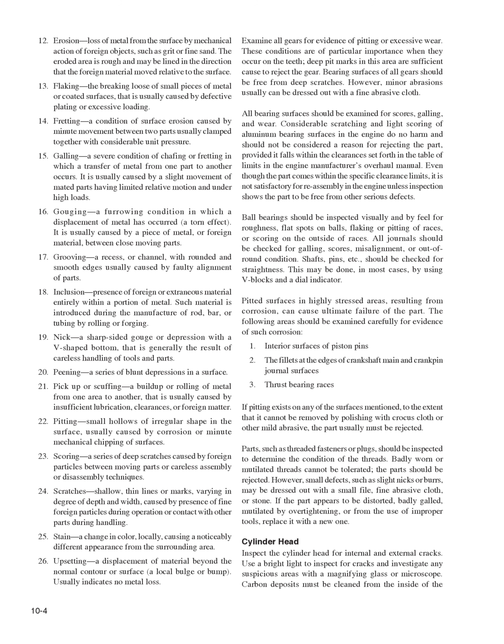All bearing surfaces should be examined for scores, galling, and wear. Considerable scratching and light scoring of aluminum bearing surfaces in the engine do no harm and should not be considered a reason for rejecting the part, provided it falls within the clearances set forth in the table of limits in the engine manufacturer's overhaul manual. Even though the part comes within the specific clearance limits, it is not satisfactory for reassembly in the engine unless inspection shows the part to be free from other serious defects.